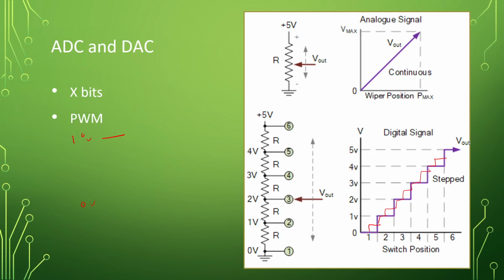What we would typically do is turn this on for half a cycle and then off, and then on, and then off, and then on, and then off. So it's 50% on, 50% off, and that would make it look like it's outputting 5 volts. Now you may be going, how? I can see the 10 volts and 0 volts. Well, it's doing it at 10,000 hertz or something, so it's doing it super fast. When the receiving device sees that, it can't measure that quickly, so it's actually averaging it. And that's how we would see only 5 volts or something.